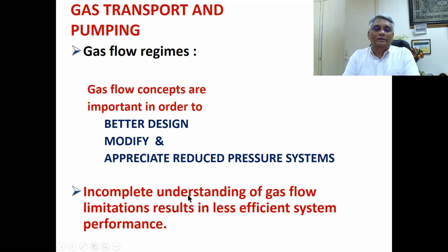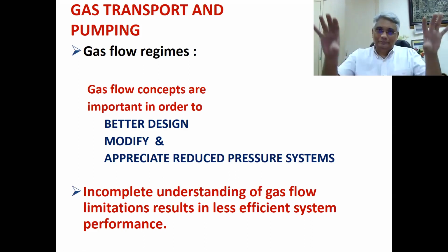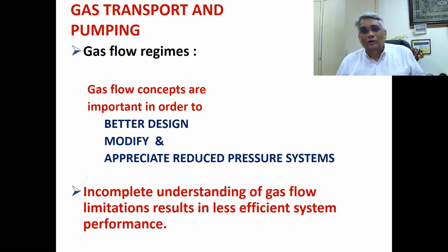Incomplete understanding of gas flow limitations results in completely less efficient system performance. This is what I mentioned yesterday. You may have a very well-designed chamber, and good pumping modules, but then the connecting entities in between are not taken care of properly. Then you won't be able to achieve good, sustained vacuum inside the chamber in order to do a thin film deposition process.